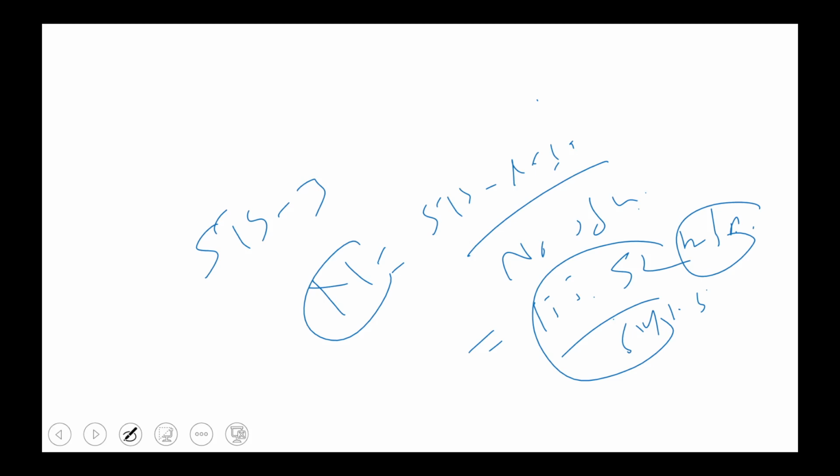If you divide the data rate of the STS-1, you want the capacity of the data packet, where each data stream is 64 kbps. The data bandwidth of the STS-1 is 51.5 Mbps and the data is in kbps. So when you divide, you have to take care of the Mbps and kbps. Either convert M into 10 to the power 6 bits per second and k into 10 to the power 3, and divide, and then solve.